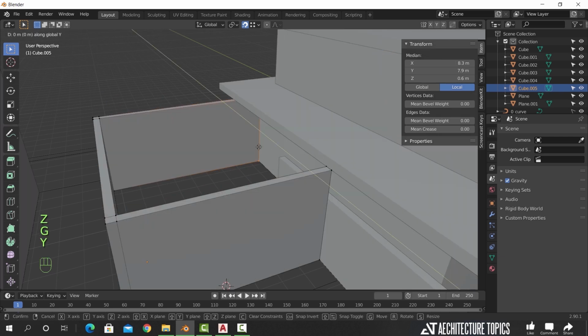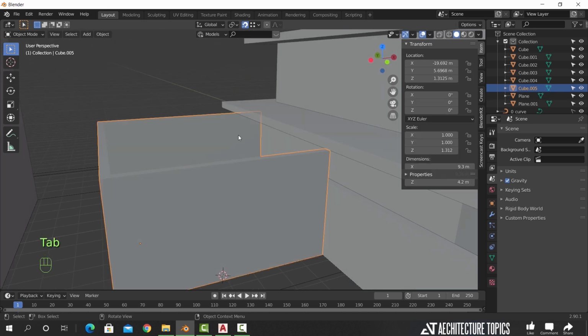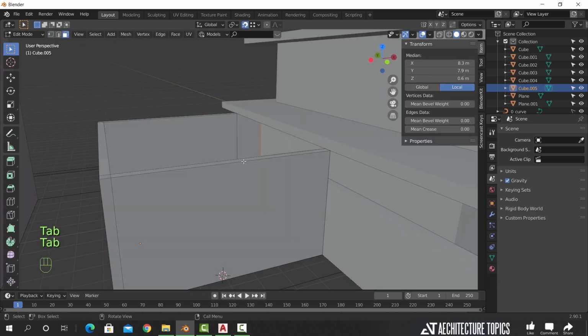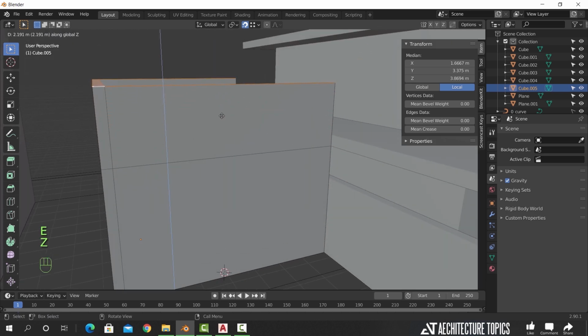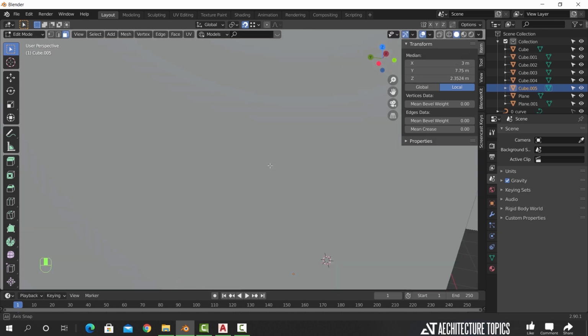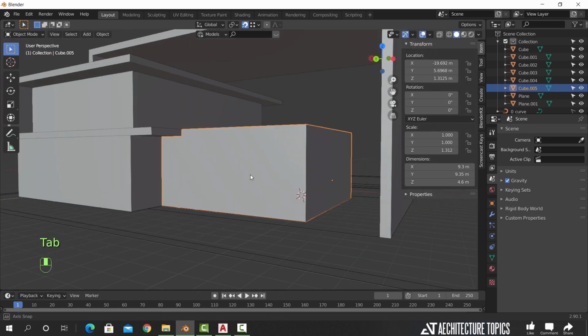I did here move those vertices back, and extend them again to the same corner. This wall now has two parts. This way we can cover those opposite walls with bridge, and it won't intersect with the main mesh. So, once you added the top part, select those two faces and with the right mouse button, hit bridge faces.